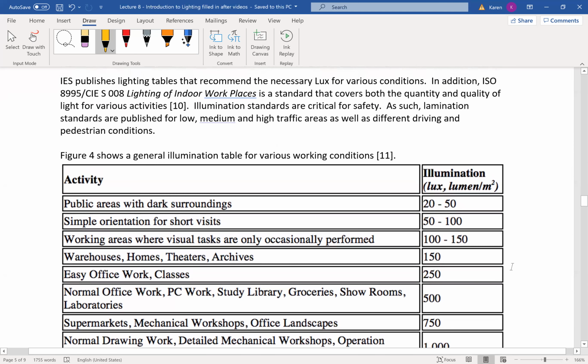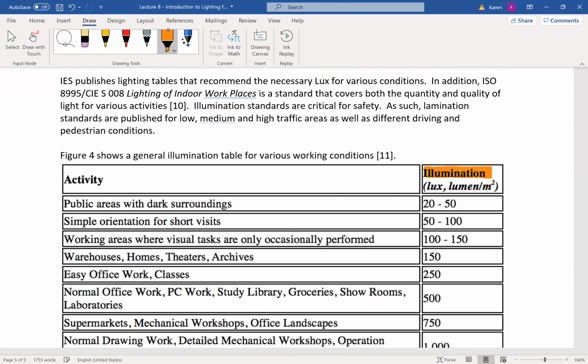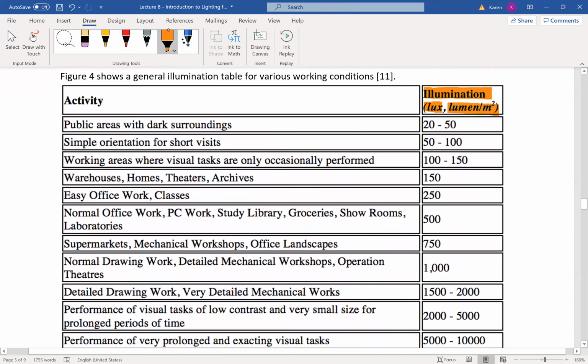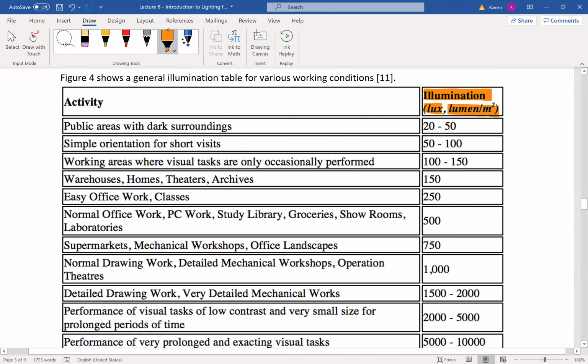Now, illumination measured in lux, and remember, lux is a lumen per meter squared. Lumen is a brightness. So there are a lot of tables for illumination, and you get more practical if you're talking about illumination. Lumens, yes, it's a science quantity of how bright something is, but illumination, you've taken the science of that light bulb and you have applied it to a physical situation where there is a meter squared of work to do that you care about.